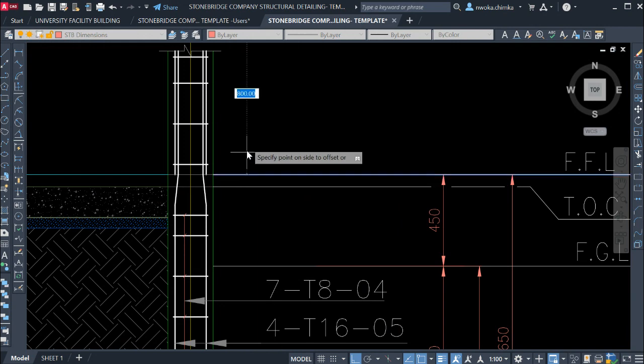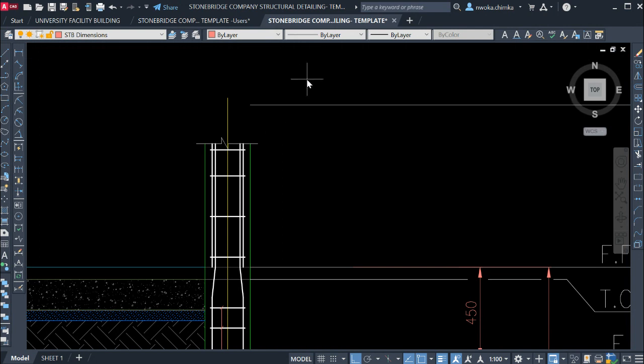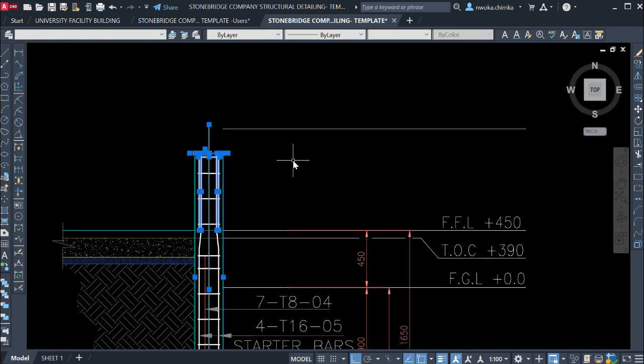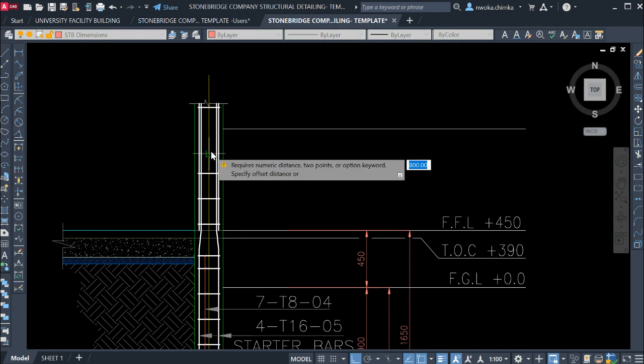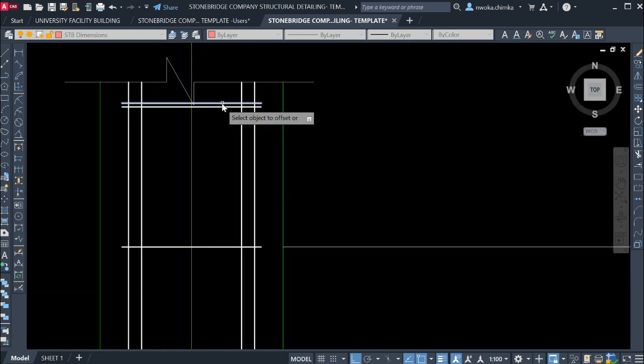From this point to this point. So you can now see that we have to stretch this line again. So stretch again, click on here to stretch again. Shift and then stretch this outward, and keep it somewhere here, and then continue to offset our spacing of 175 for this link, because we have already stretched this again. So 175 to offset this, and then this also, and then this also. You can see that. Sorry, just take off one out.